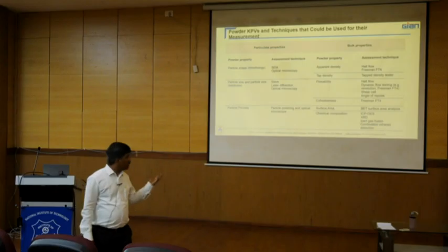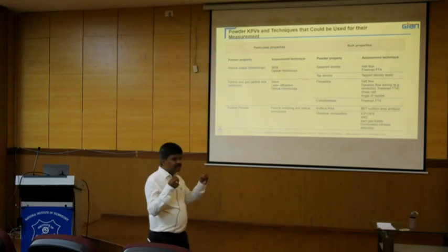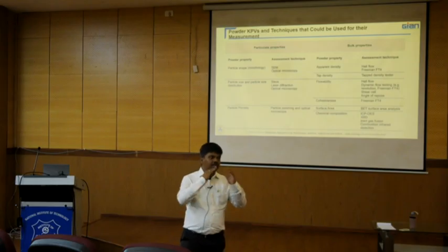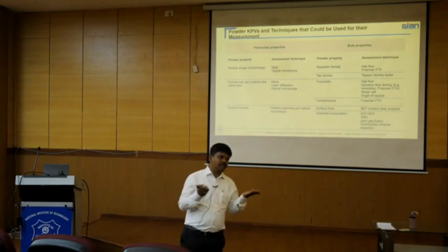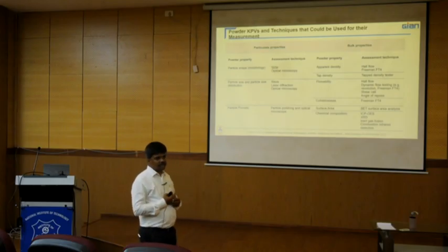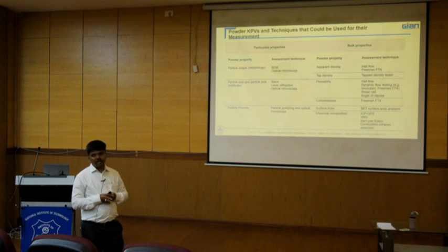Optical microscopy or SEM works only if it has surface porosity. If the porosity is inside your powder particles, then we need to go with non-destructive testing only. X-ray CT is the best way to analyze the porosity inside the powder particles.